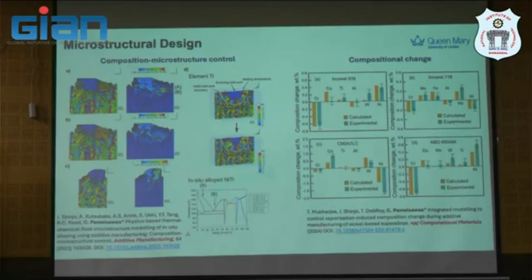It's actually heterogeneous solidification. You will see some distribution of the nickel and titanium separately, and that means there will be some grain formed inside the melt pool before surrounding with liquid, so equiaxed grains may form something like that. So this is the insight that we provide from the nickel titanium system, based on a simple binary system.